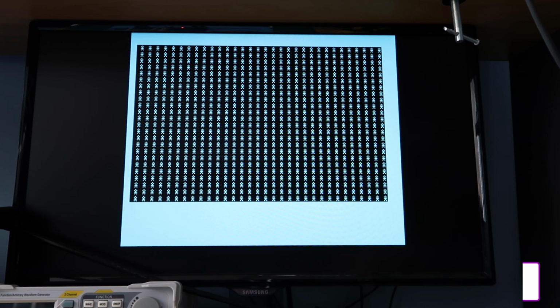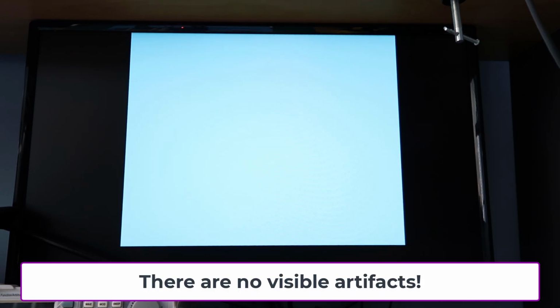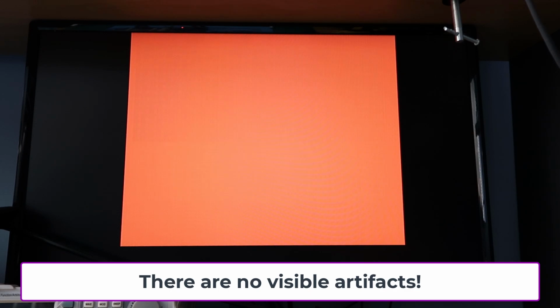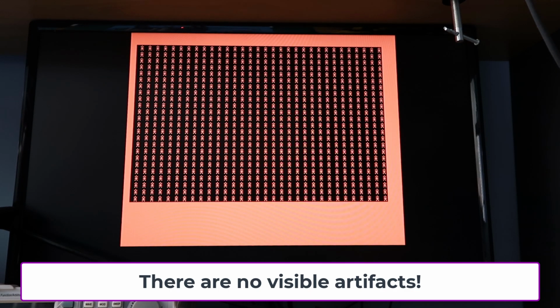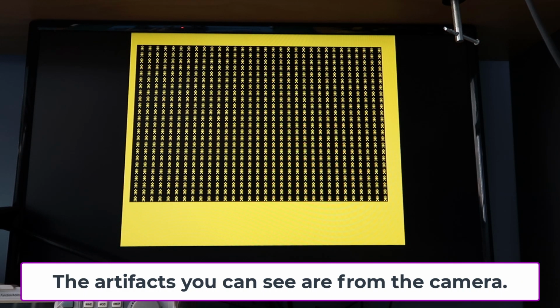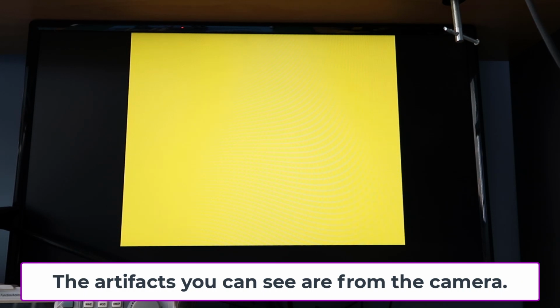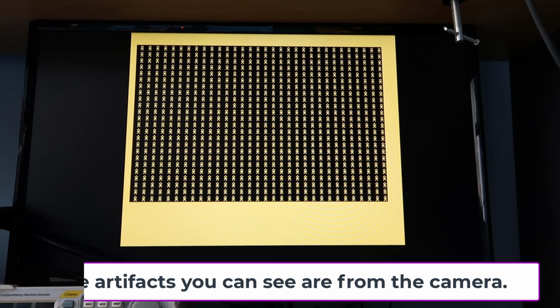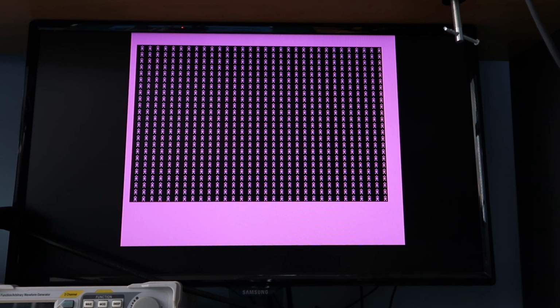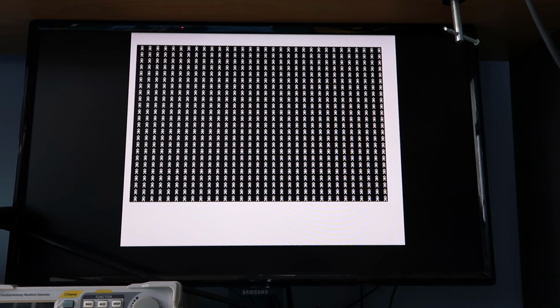So the last step to complete this board will be to solder on the TMS RGB module, then modify a Genesis 2 video cable to remove its embedded output resistors. Then I should have a nice SCART lead to plug directly into my analog CRT, which will be very interesting to finally see the good quality VDP output displayed on a retro CRT display.